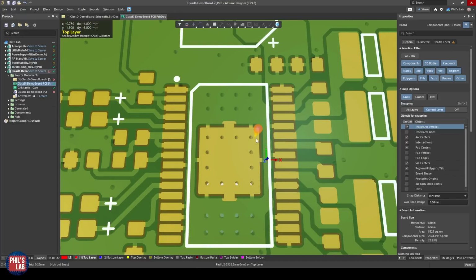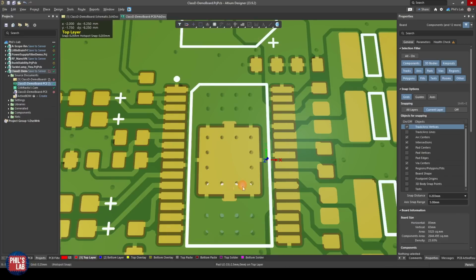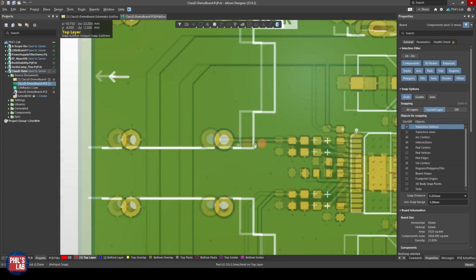Just to reiterate here, our thermal source is this IC, and the thermals will pretty much occur directly in the center, which will be bonded to our PCB via solder into our thermal pad, and we want to transfer that heat away as quickly and efficiently as possible. And the way we can do that, for example, is using a top ground plane, but also digging down with vias, grounded vias, into our bottom ground plane, which acts as a fairly sizable heatsink.